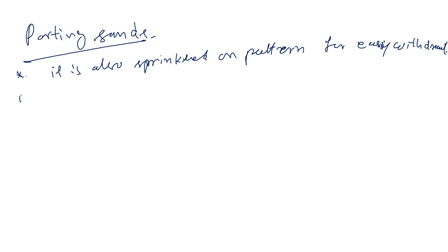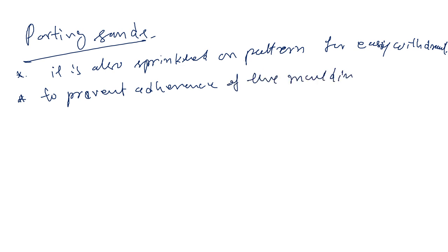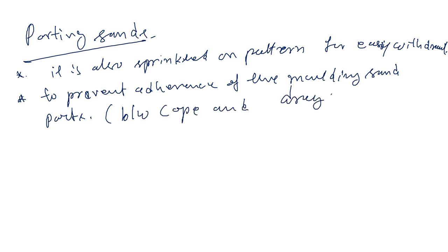Second is to prevent adherence of the molding sand parts, like between cope and drag parts, and this helps in easy withdrawal of the pattern and easier separation of cope and drag at the parting surface.